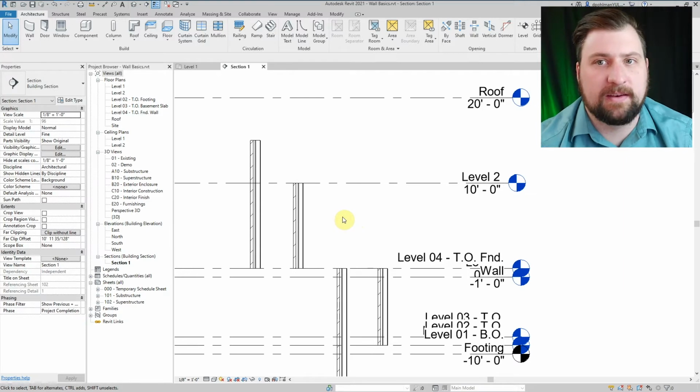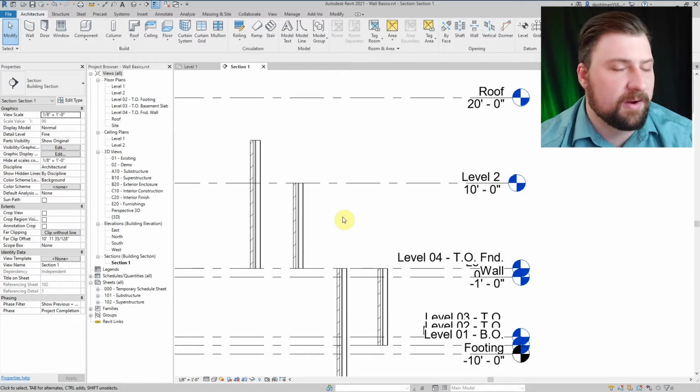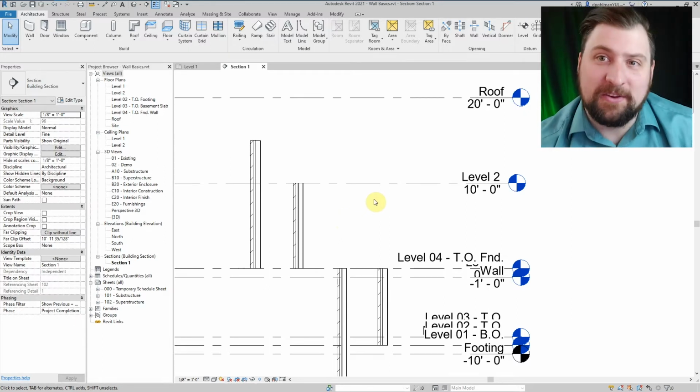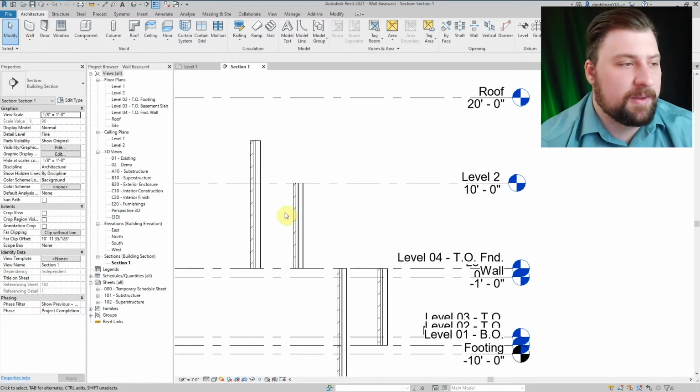It'll save you a lot of time when there's a change in the level height and you have to go back and change how all your walls are associated and what their heights are, where everything's located. It's a nightmare, trust me. I've done it before. So always go and constrain your walls to the top and the base.